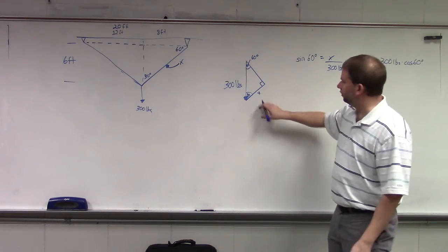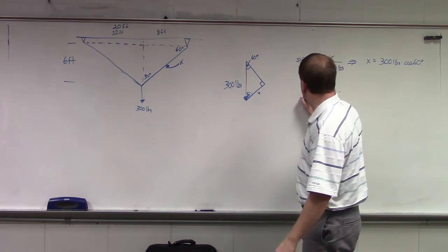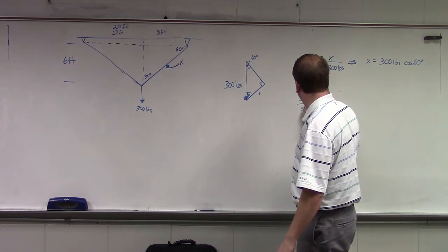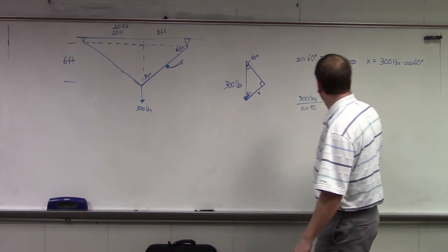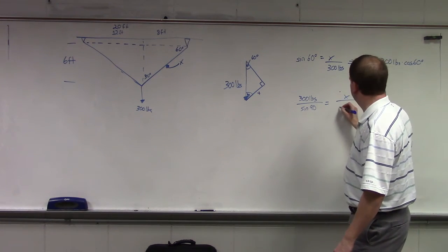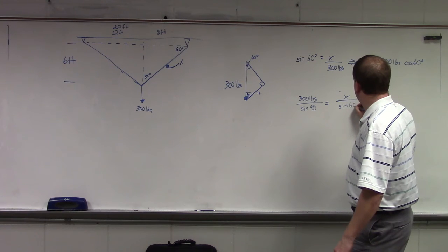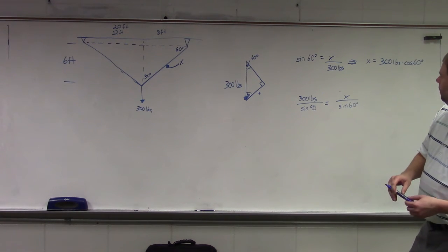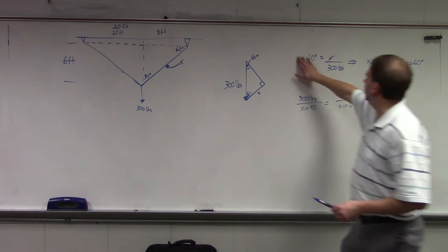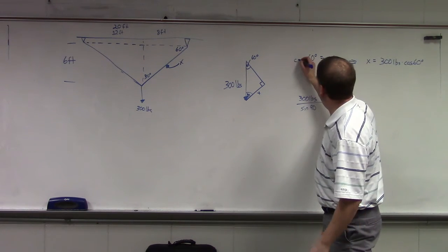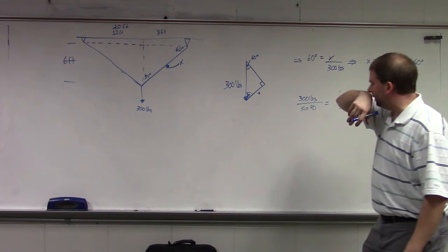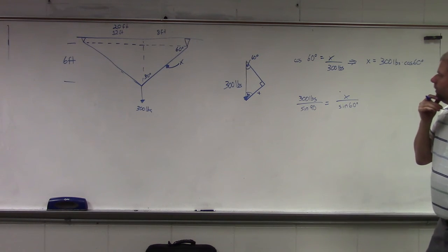And if we wanted to use law of sines, we would just say 300 pounds is to sine of 90 as x is to... What are we times it by, the cosine of 60 degrees? Sine of 60 degrees. For the top one? Oh, yeah, sorry. Oh, okay, because you had sine there. Yep. No, I wrote sine initially, and thanks for pointing that out, Marshall.